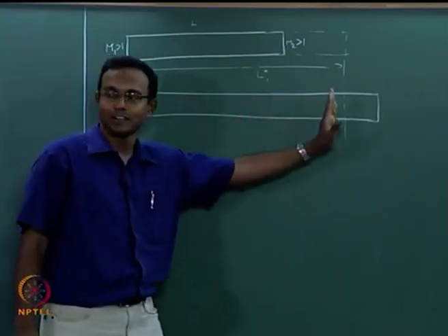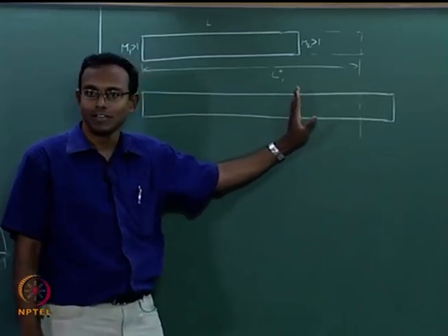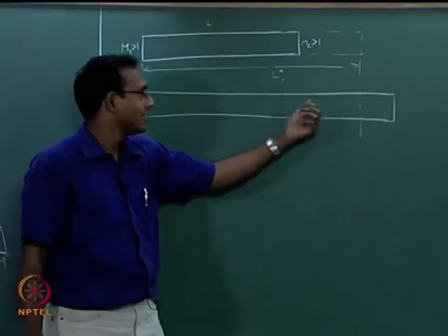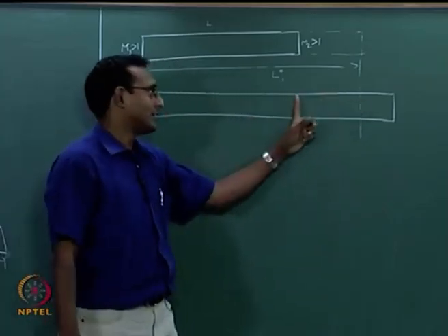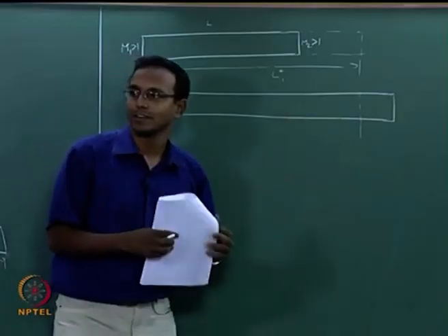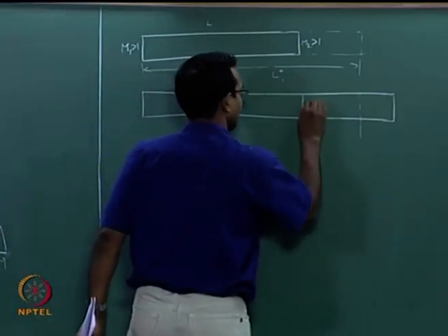So there will be a point where that set of compression waves comes to an equilibrium against the flow. It is like a treadmill, right? The shock wants to run ahead and the flow is going this way, and it will come and stabilize somewhere here typically. So there will be a shock sitting here.